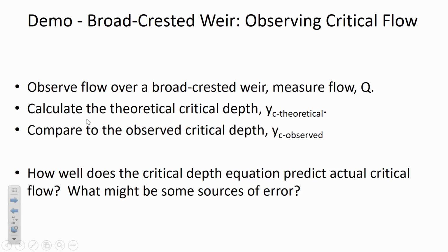All right, so let's go down to the fluid mechanics lab and let's turn on the flume. I've got the Broad-Crested Weir set up in the flume, and we're going to go through this process of observing the critical flow, measuring the flow rate, and trying to compare the theoretically predicted critical depth to what we observe.